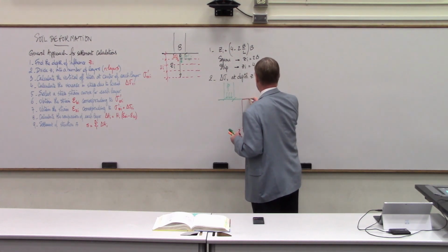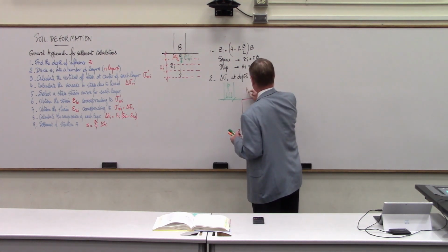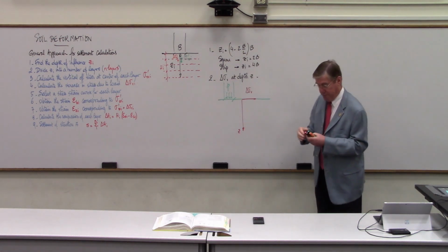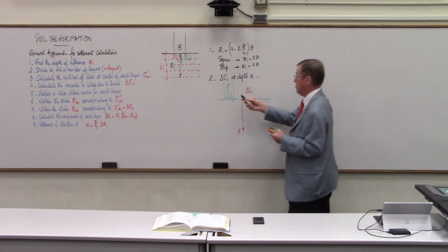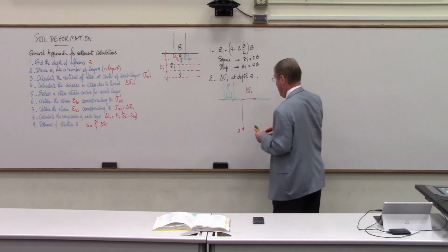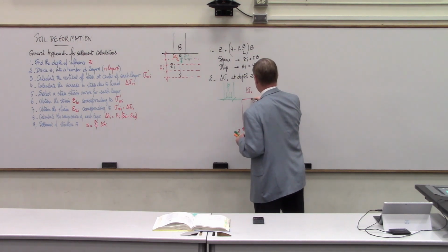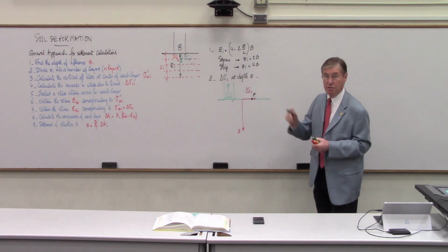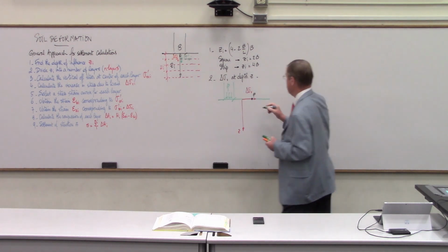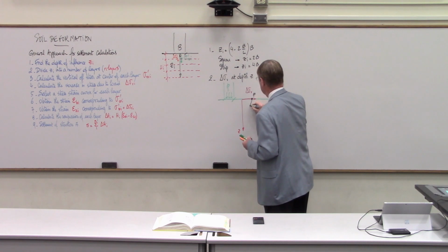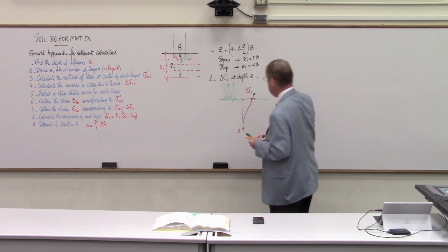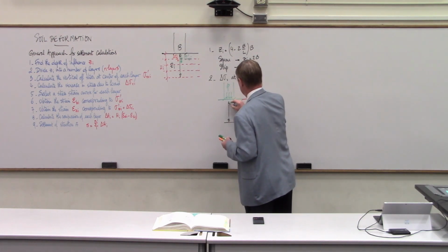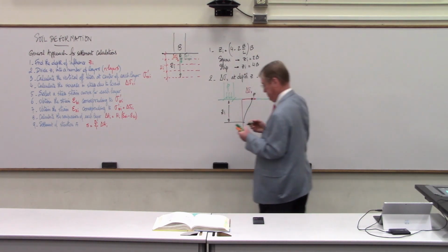So we're going to put here the increase in vertical stress at any depth Z. At the ground surface, we're going to have the value P. The increase in stress at the ground surface is the value of the pressure under the foundation. And then this stress will decrease with depth down to something that's quite small at a depth equal to Z sub I.